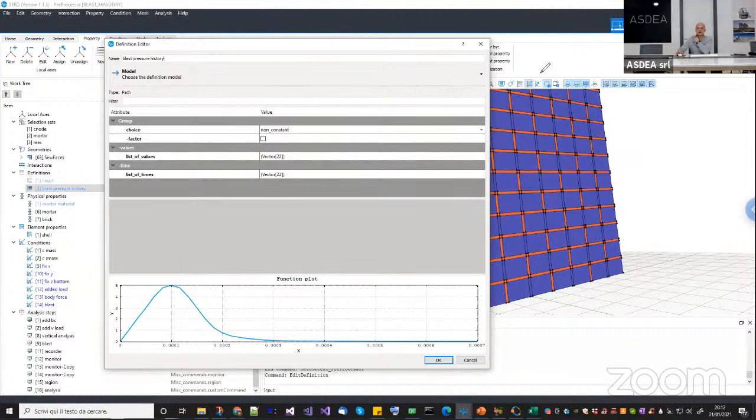Next question: could you recommend a procedure to determine frequencies for Rayleigh damping coefficients? Actually, it is stated by some of the national codes, but you have to take the first one and the last one that provides you a certain amount of participating masses. I think it was 85%. Now it depends on the situation. Sometimes you don't reach them, sometimes you don't want to include all those higher frequencies. But let's say you have to compute the range of the frequencies you need to do a certain excitation of masses.